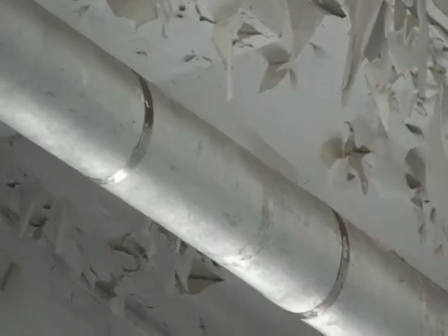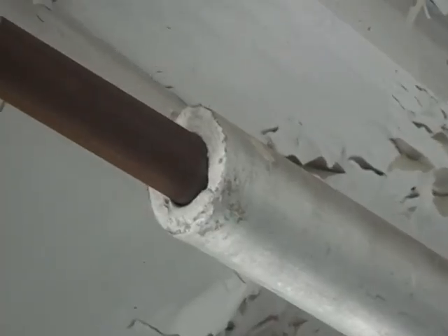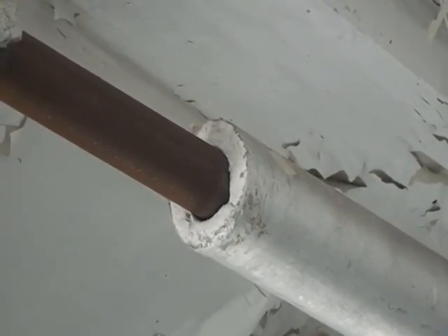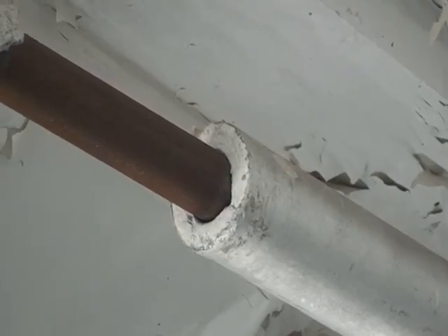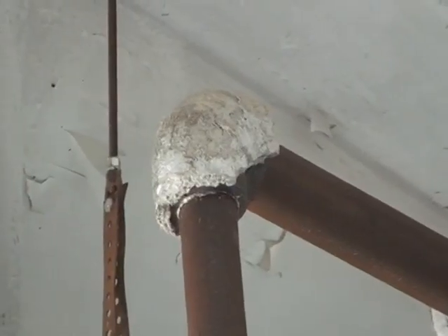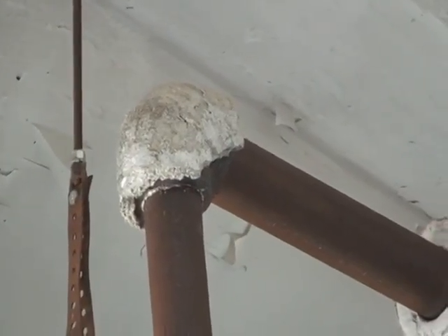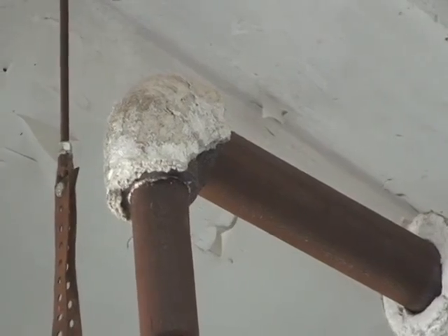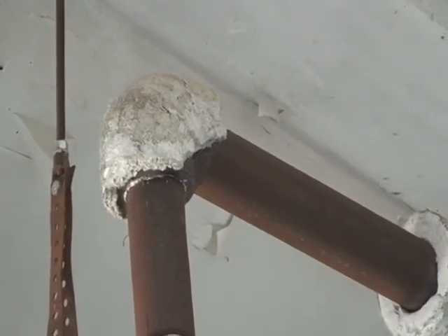Here's an example of an insulated steam line. It's got 2 kinds of asbestos insulation on it. On the pipe run itself, it's got preformed halves that you can see has the metal clad on the outside held in place with the steel bands. If you look at the elbow, you can see a mudded insulation which is formed in place over that fitting. Both of those would be considered examples of friable asbestos containing materials.